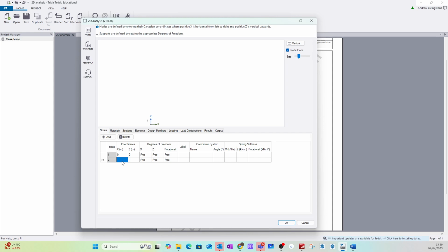And then we'll go along the x-axis, and it'll be 2 meters up 0, and then it'll be 3 meters up 0, and then it'll be 8 meters up 0, and then 10 meters up 0. I'm going to hold nodal point number 3. I'll fix that in horizontal and vertical, and I'm going to hold nodal point number 4. I'm going to fix that in just the vertical.